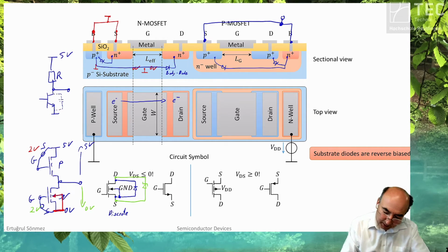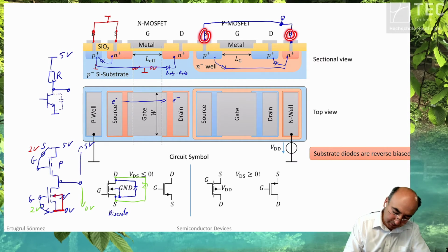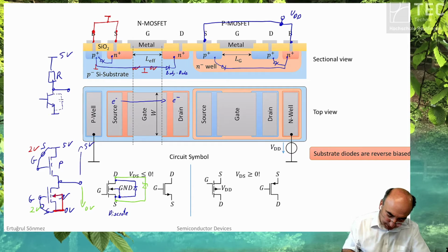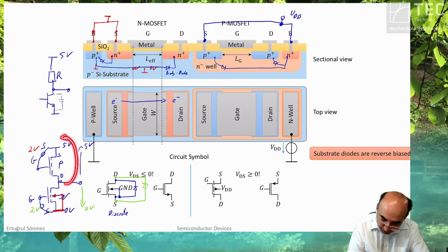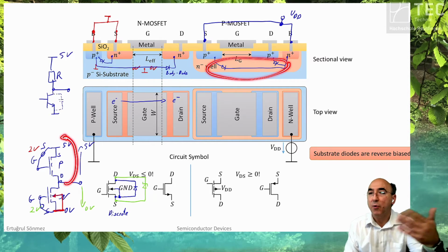Sorry about that. You have to connect the bulk also to the source, but now the source has the highest potential on your circuit diagram. So it's called VDD. And this source potential has the highest value you can have in your circuit, your integrated circuit. And now if this drain compared to this source is higher than the supply voltage, then your diode is forward biased.